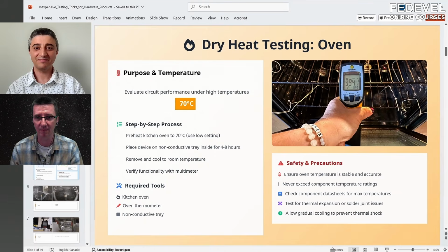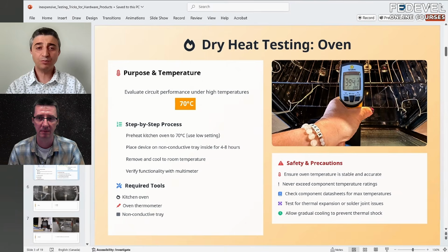So this is the biggest problem. The problem is not 85. Most components, if they are kind of passive, they still, if you buy the industrial version, will work. But there are components which are going to heat up and the temperature is going to be higher than 85 degrees, and this is going to be a big problem. No, I agree with you. To your point, Robert, for that reason we do proper calculation of the thermal of your design.